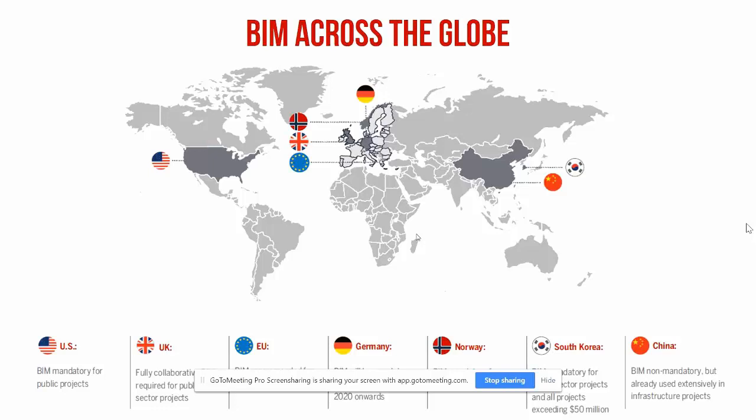Level 1 is very much firms designing using 3D, BIM-based CAD software and clash detection tools. Level 2 is companies exchanging some information in a common BIM format, perhaps where designs and blueprints are created in 3D CAD. And level 3 is that all parties are working from a single shared BIM model stored in the cloud. That shared model is then also used as the basis of all relevant communication and integrates everyone's work.